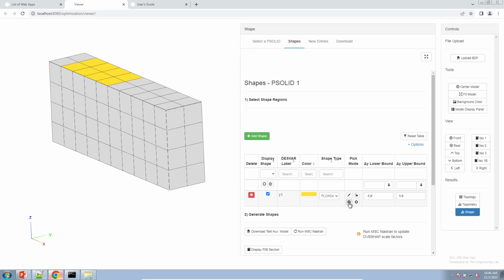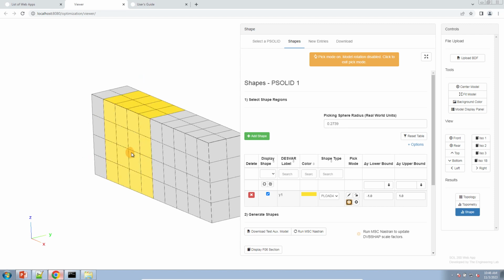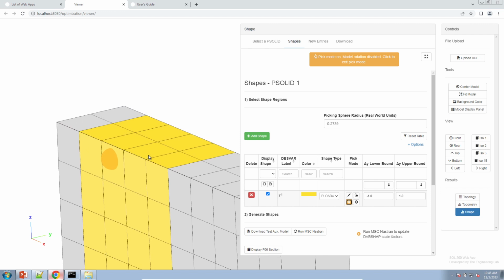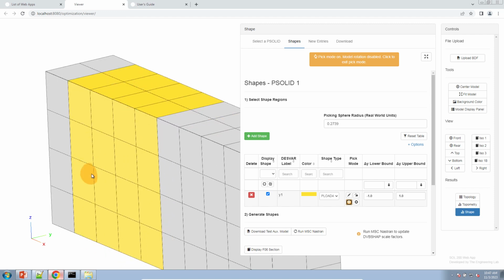Click on this plus icon. Do you see me circle with the mouse cursor? And drag and select these elements. And the difference is the following. The primary element faces will either contract or expand, and they're colored in a darker color. The lighter colored faces are the secondary faces. These faces are going to stretch during the shape optimization.